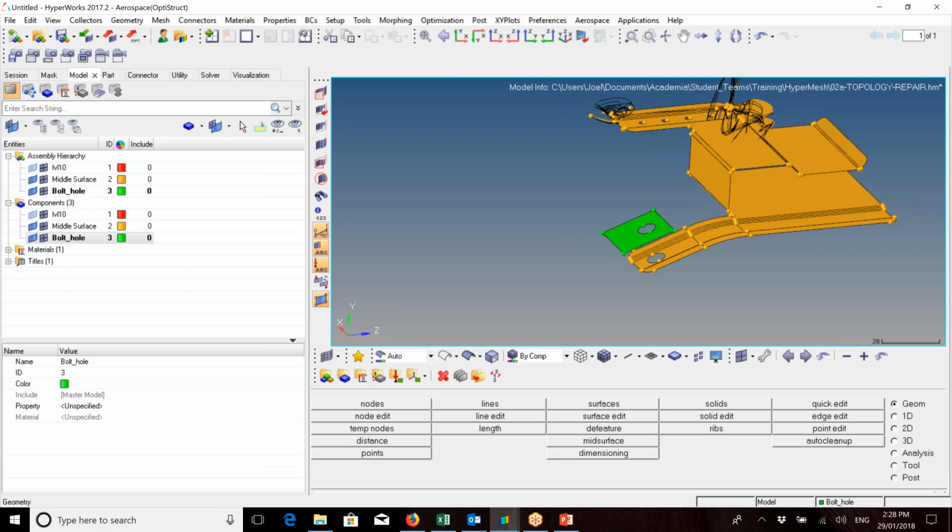By creating your 2D mesh first, it provides a lot fewer elements to have to go over and check, and then when you create your 3D mesh, which I'll show later on, you can actually connect it to your surface mesh. So you know that your surface mesh is well created, which means your volume mesh is something really good to build off. As well as for mid-surfaces, and which I won't show today, that'll be next week, when you're creating your properties, you give it a shell element card, and then you can give it a thickness, so that way you can pull out the stresses and perform your analysis on your mid-surfaces.